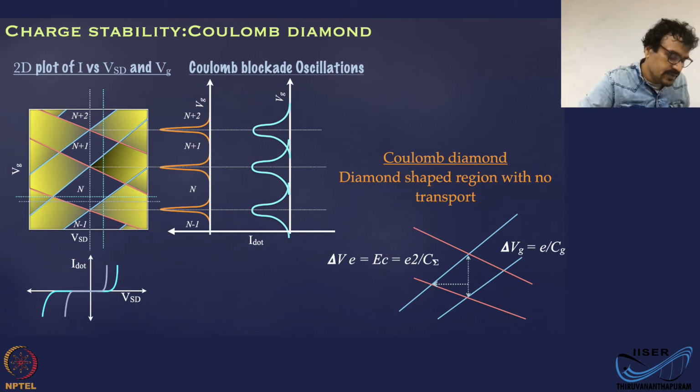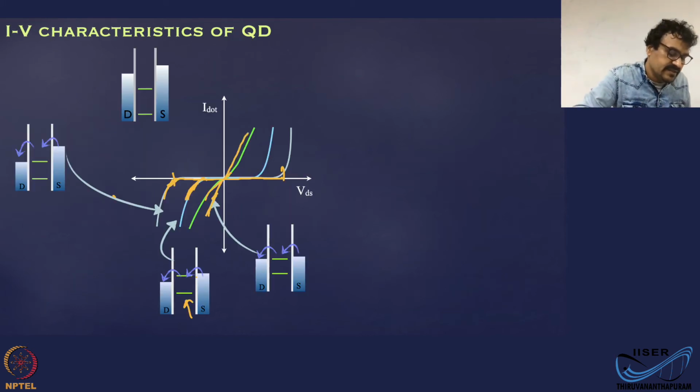You can offset this by a small gate voltage as shown here. Then you can reduce the blockade region and get current turned on at a lower bias voltage. This is basically the same thing we discussed in this slide, where you can apply various gate voltages and reduce the blockade region.